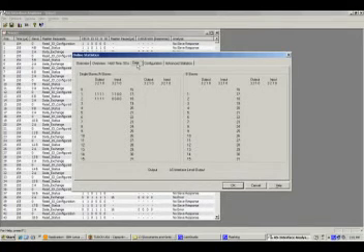I can go here to the data tab and again turn on and off input number 0 for slave address number 2, and then on the other address here, address number 1 happens to be an ASI node that has 2 in and 2 out on it, and I've got a proximity sensor plugged into it for input 0 as well, and so you can see that you can monitor that packet as well.